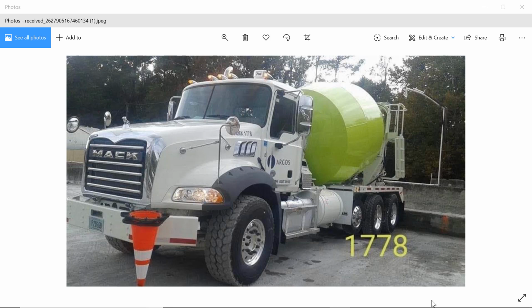Moisture content in percent is equal to 100 times (1,509.6 minus 1,476.4) divided by (1,476.4 minus 295.3), which is equal to 100 times 33.2 divided by 1,181.1, which is equal to 2.81%.